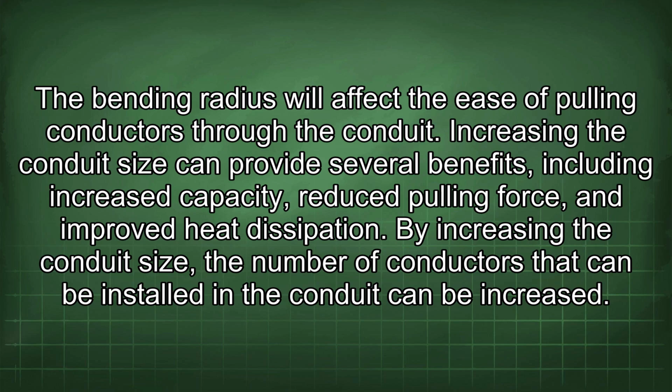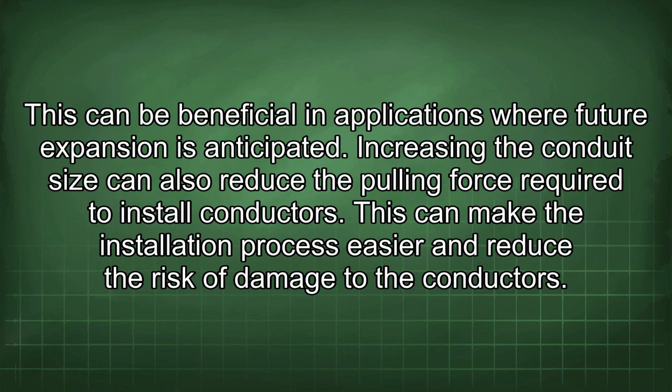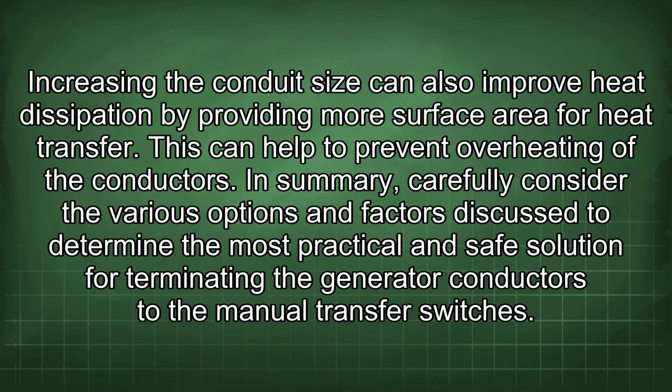By increasing the conduit size, the number of conductors that can be installed in the conduit can be increased. This can be beneficial in applications where future expansion is anticipated. Increasing the conduit size can also reduce the pulling force required to install conductors. This can make the installation process easier and reduce the risk of damage to the conductors. Increasing the conduit size can also improve heat dissipation by providing more surface area for heat transfer. This can help to prevent overheating of the conductors.